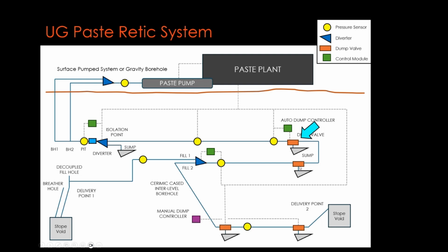So we have a dump valve here that can be used at the end of a long run, and it's a higher pressure rated dump valve at 25 MPa, and it's used to reliably evacuate the upstream paste mixture and enable a successful system flush to the dump point. The dump valve seat will reseat post-actuation, allowing the application of the upstream pressure to clear the downstream blockage recovery.